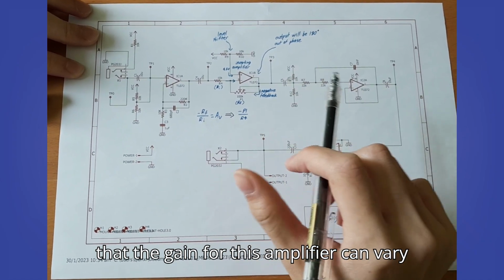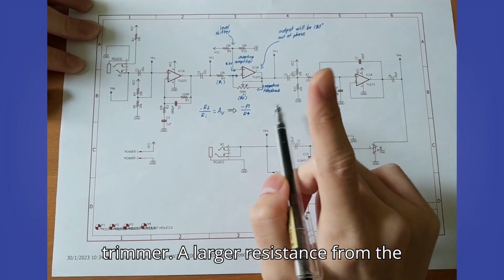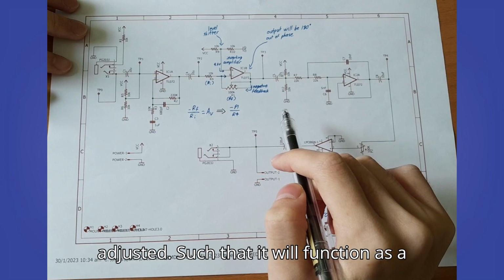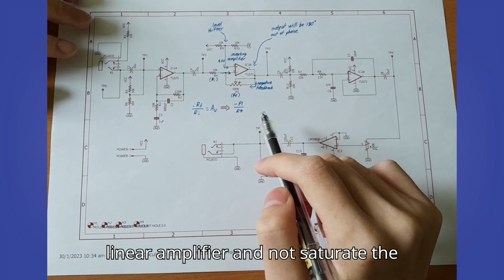This means that the gain for this amplifier can vary based on the resistance set by this trimmer. A larger resistance from the trimmer will result in a larger voltage gain. The gain can be carefully adjusted such that it will function as a linear amplifier and not saturate the output voltage.